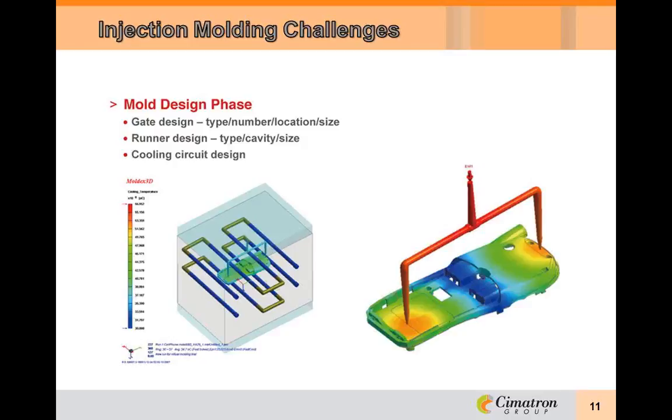The primary tasks of an injection mold include the accommodation and distribution of the melt, precise temperature control to properly solidify the material, and ejection of the molded part. Additionally, a mold has to provide good tooling or steel conditions and mechanical functions such as slides and lifters, all while holding tight tolerances on the part after the warpage and shrinkage of the solidification of the material.